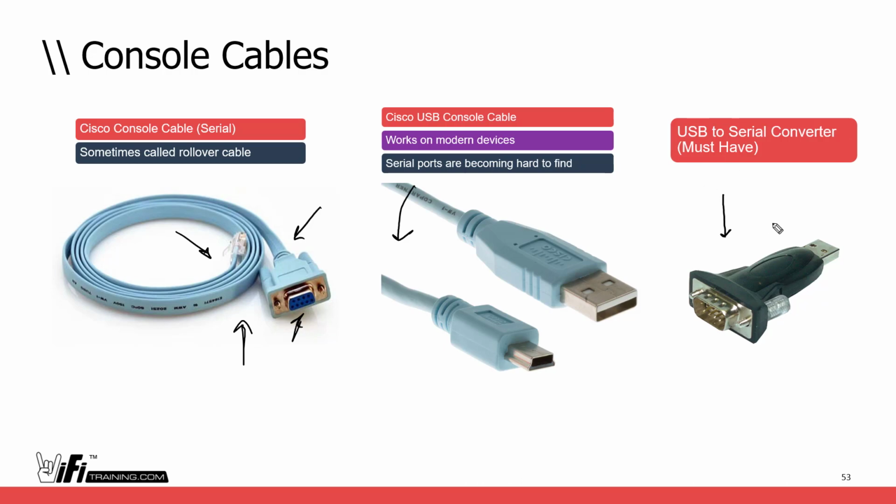Now, a word on these USB to serial converters. Standardize as a company on which ones you're going to use, because the drivers for this stuff can be ridiculous, especially with Windows 7 and Windows 8. The drivers can be just an unbelievable, painful problem, even in Windows 10 sometimes, because these are made very cheaply sometimes, and they sometimes come with a mini CD-ROM. Nobody's even got a CD-ROM in their laptops anymore. At least I don't. I haven't had one in the last 3 laptops I've had. So make sure you get the drivers for it.